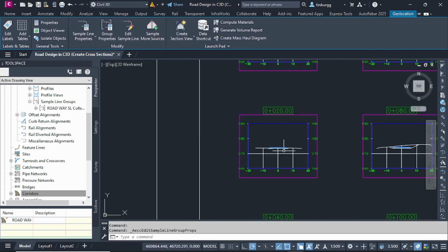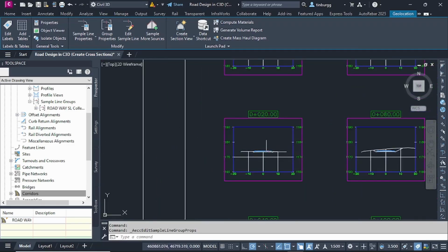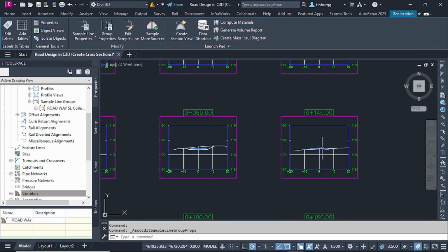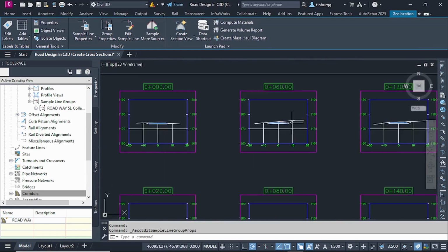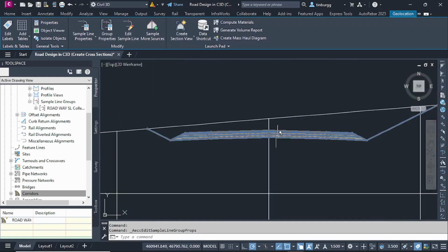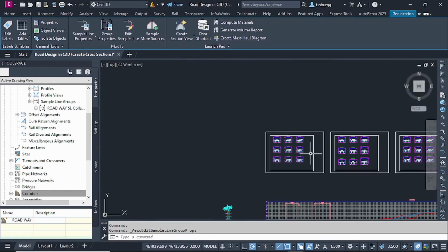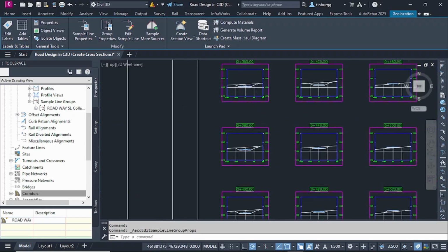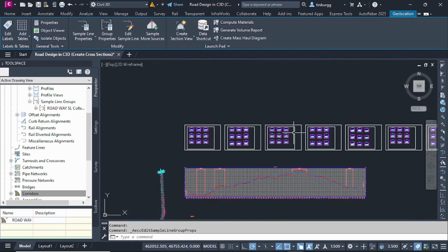You can always change the data that you are sampling in your sections by just clicking on that, you can alter the sources from which you are sampling. So these are my sections. Next, we are going to see how we can place these on sheets. So let's go ahead and place our sections in section sheets.